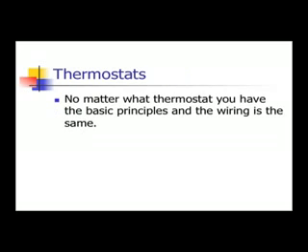When you're dealing with thermostats, know what voltage is controlled. Do not touch a broken mercury thermostat. It is environmental waste and can burn you severely. Make sure you dispose of any mercury thermostats in appropriate designated spaces.